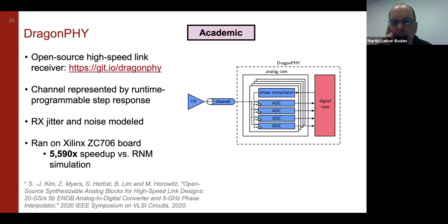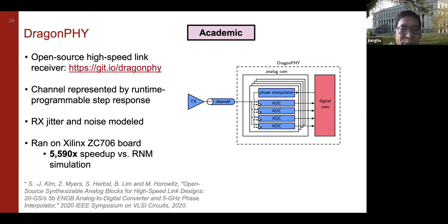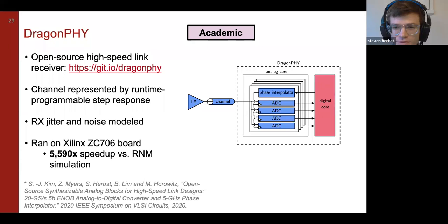You're recommending, say, Palladium and the like? Yeah, I think that would be interesting to look at. Thank you. There's a trade-off there, though, that I should mention, which is that in general, there's about a 10x performance reduction to go from a custom FPGA setup to a commercial emulator.